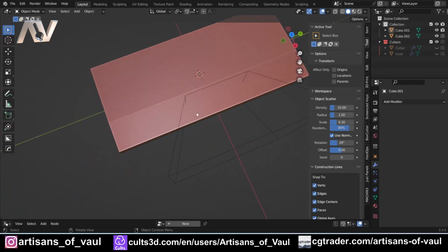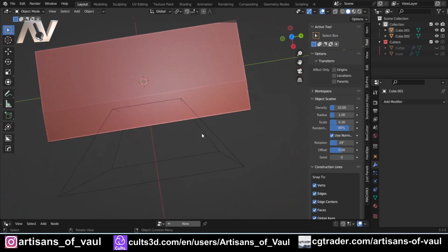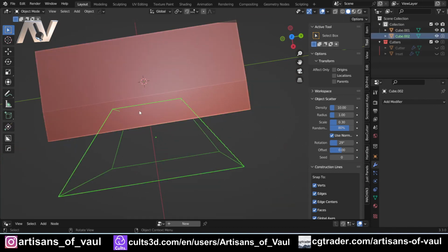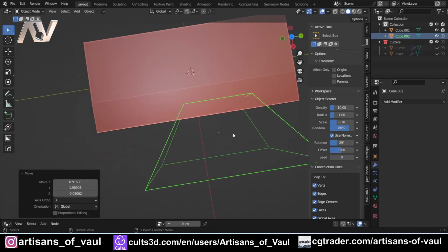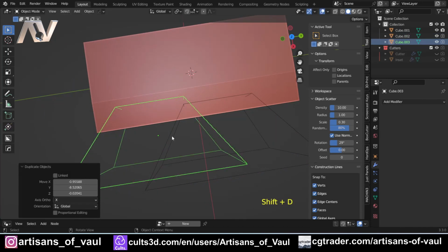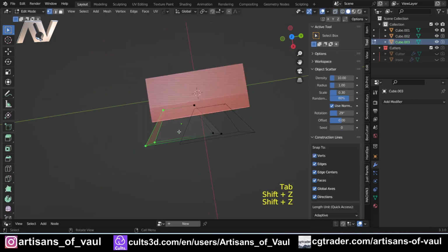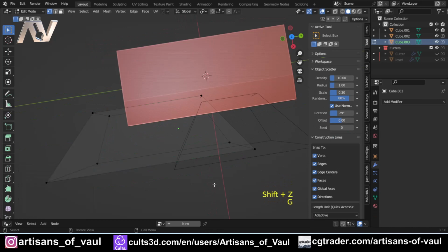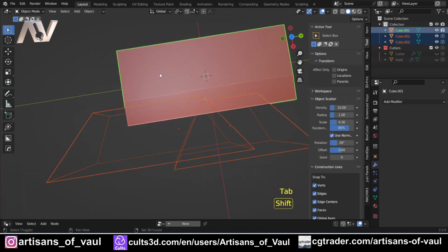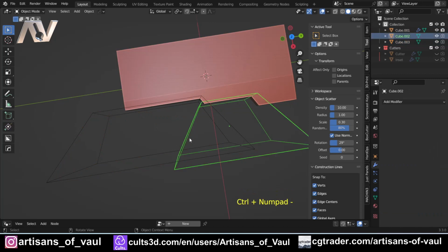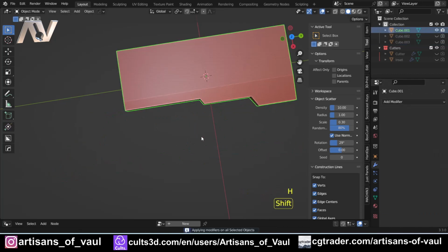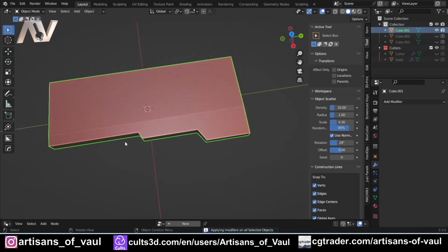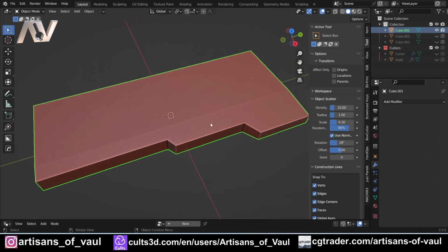And we're also going to make something a bit more complicated, and I'll demonstrate another problem. So let's do something funky. Let's decide that we actually want to have this more extreme shape. So I'm going to go something like there, and then let's Shift and D, and then go to there, and then G and Y, and let's cut both of these from our object. So Control and minus. And that's going to be our shape. So I'm going to hide that, and then I'm going to apply these. So apply all there. There's a link in the top right hand corner if you don't have apply all, and it'll show you how to get that and why it's quite useful to have.